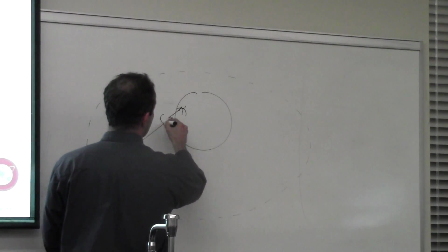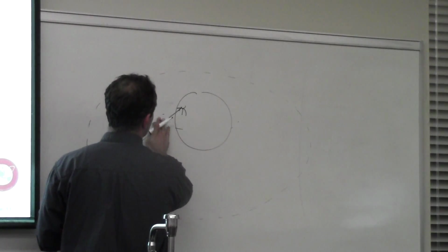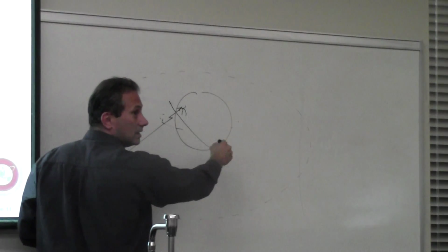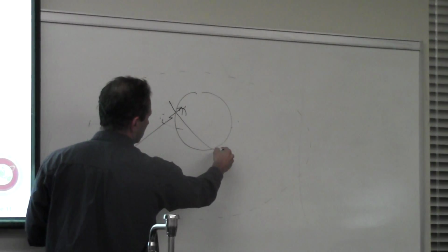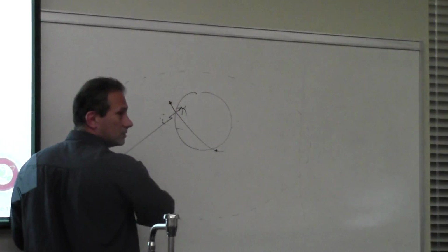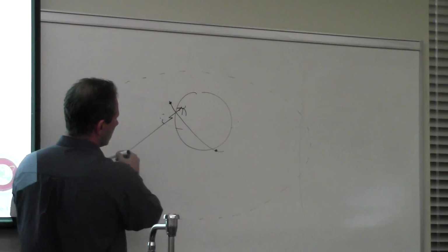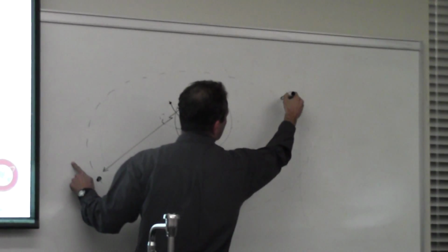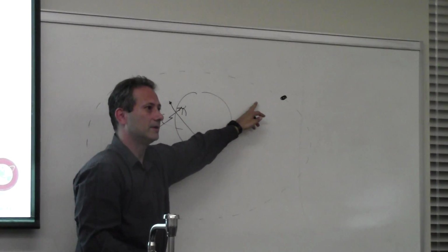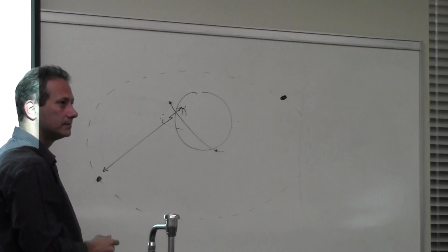But think about a LEO satellite. I'll put it in an inclined orbit, so it zooms like this, right? You can see that its position changes. When it's here, it needs to point in this direction. When it's here, it points in a different direction. Furthermore, when it goes behind the Earth, it needs to find another satellite to point to, this one. So as long as it's in this quadrant, why not just have a link with the TDRS,